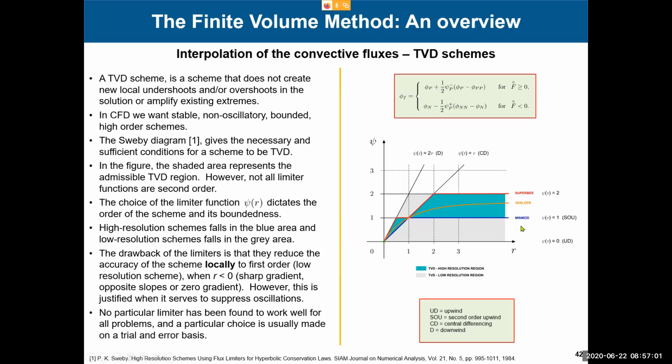Here I'm just showing you 3 methods, probably the ones I like. For me, the best one is the Van Leer. You see that it's very continuous, a smooth one. Instead, the min-mod is known as diffusive, because you see here that it is in this limit. Superbee is known as compressive. It's also in the limit of stability. But these are TVD methods, high accuracy. This is what we want.